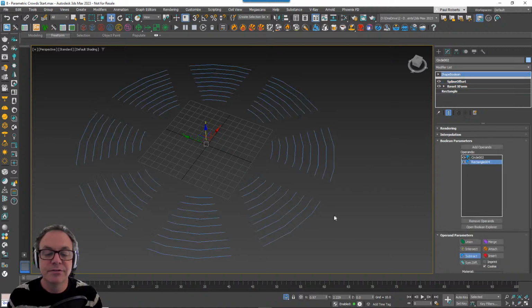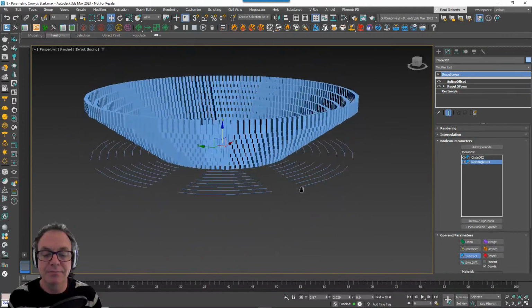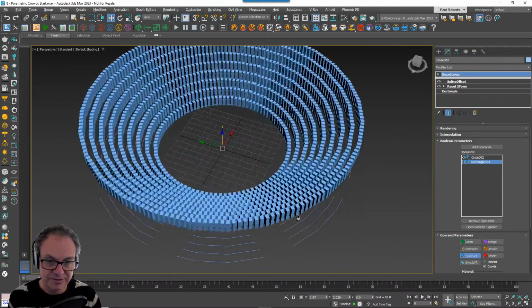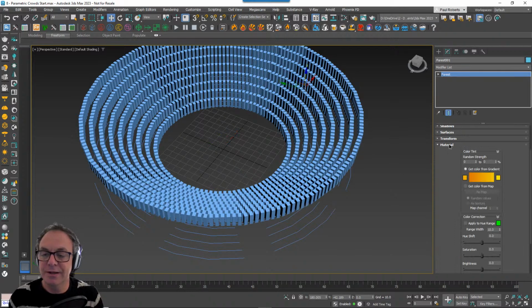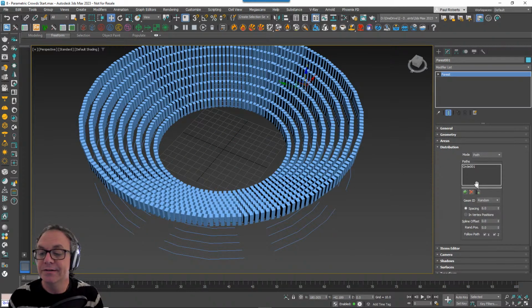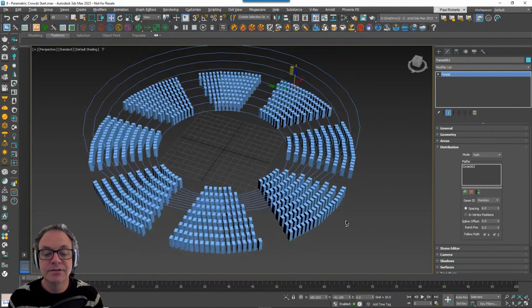There you go. So that's fine, but the only issue is that the shape Boolean flattens the spline. It always does. So when I come into Forest Pack and assign the scatter to this new spline I've just created, obviously it goes down to the ground. So how do you fix that?